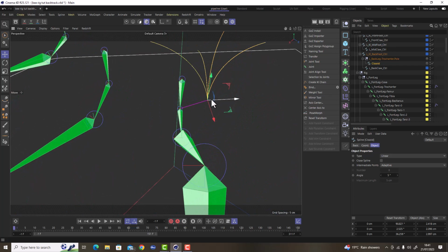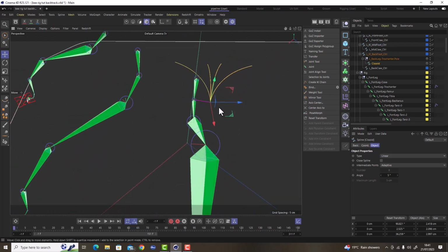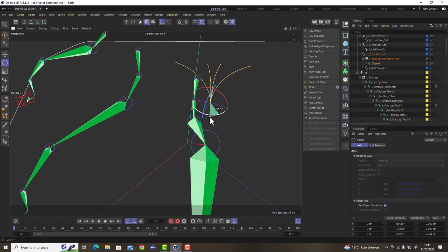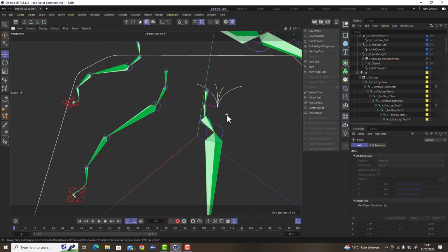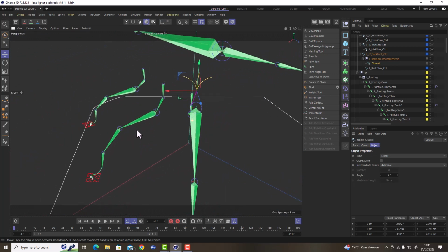The only thing that it's not done is it's not orientated the way I would like it. I would like the Z to be facing forwards, so I'm going to go in there again and just rotate it one more time. This time 45 degrees, or 90 degrees shall I say. And now this controller is going in the same direction as all the other controllers.